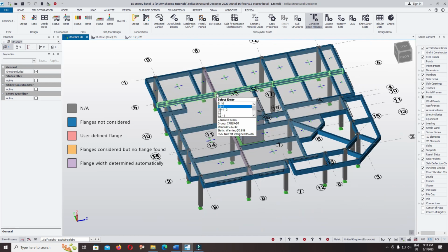You can check the picture. Slab 1 is aligned at the top with the beam, and slab 2 is at a different level. You can check: slab 2 is not a validated candidate, so the software cannot include the right slab as the Flange Beam. The left slab can be considered as the L beam. In this section you can check the picture below: the alignment at the top of the beam, the right slab with the beam, and the slab overlap. Check the overlap. Is the slab overlap greater than 50? Slab 1 is a validated candidate to act as a flange.